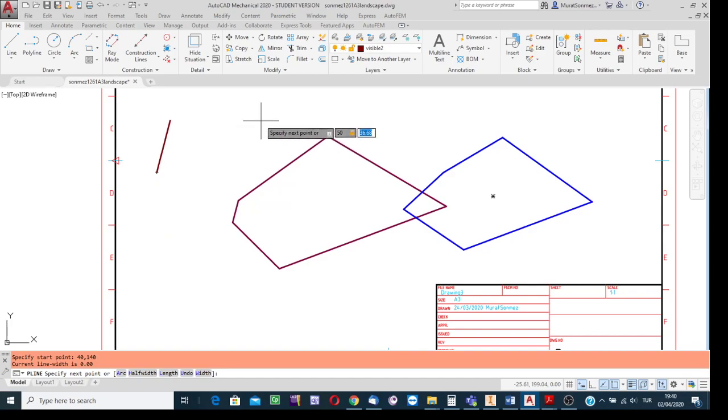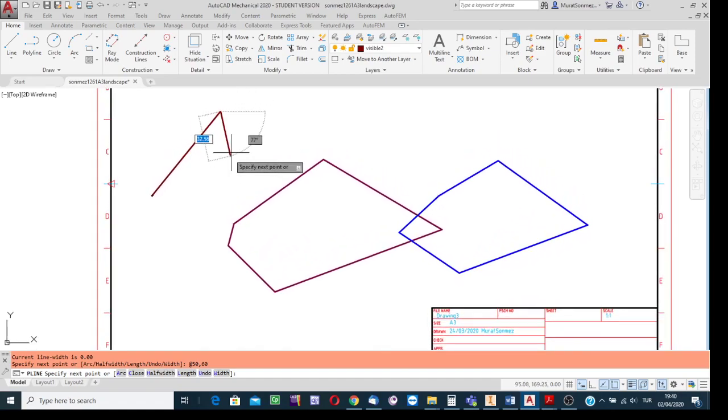I'm going to create the line upwardly inclined, so write the delta y value, while the third box along the train is to accept the delta y value as a positive number. Say that delta y is 60. Positive. Press enter. That is it. Yes, the line has been created. And then continue. Well, let's see one more example, one more exercise.